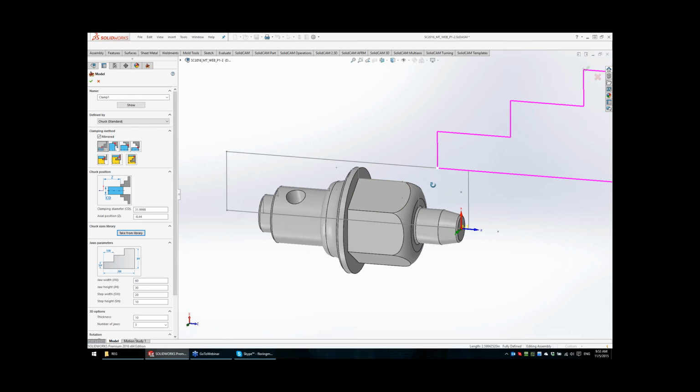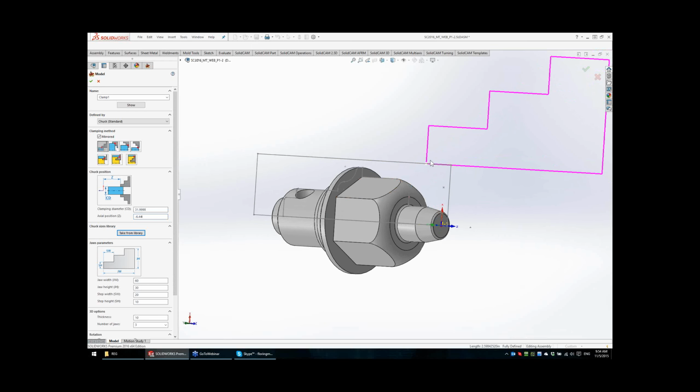When is it important? When the user uses manual transfer and takes the part manually and transfers it to the other spindle. Then we take the information from here. In any other case, with transfer with the MCO, we take the information from the MCO. So I will create an MCO. I don't care about this position now, but I want to catch the part.